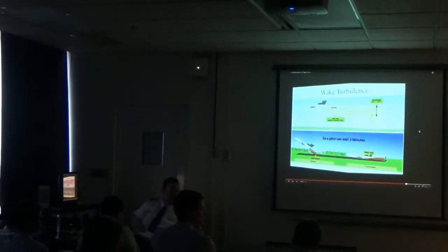What about the engine? Would that cause wake turbulence? Not so much. It's the wingtip vortices that are the biggest cause of wake turbulence. The engines, especially the jet engines of those aircraft, not so much. They create thrust, and the thrust can be dangerous. But most of the time, you're far enough away from the aircraft that the thrust of the engines doesn't affect you.